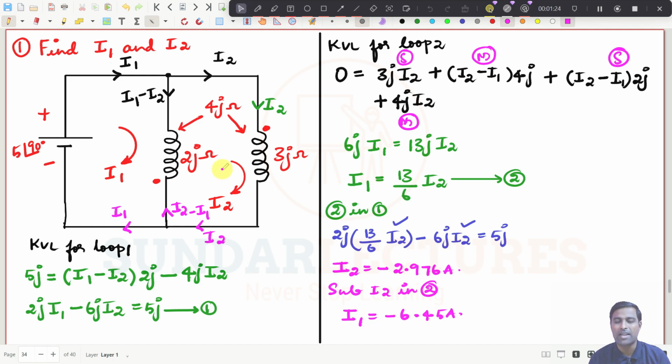See, very clearly you have to understand. If you are writing self-induced EMF, straight away put the plus. Straight away it is the positive value. And if you are going for the mutually induced EMF in a particular coil, then you see whether current is entering in one coil and in the other coil. You have to compare two coils' currents. If both coils' currents are entering through the dot, then put plus. If both the coils have different current directions, you put minus. That's all. Very simple. Students make mistakes while writing the mutually induced EMF. They will write this value instead of this value. To avoid that, you have to be very careful writing these expressions, right?